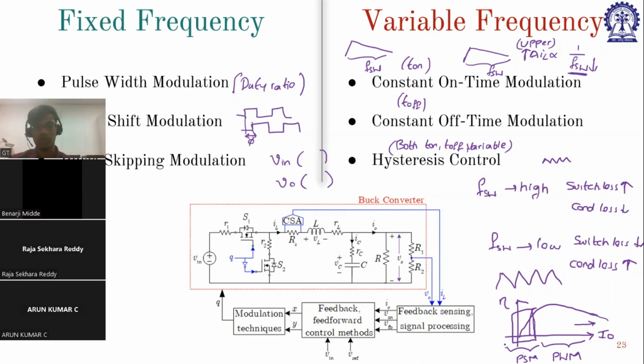Okay, during some cases, even if we select the inductor having, say, 20% peak to peak ripple, while designing or choosing this L, we will be considering the peak, maximum load current. Worst case, yes, for everything you'll consider the worst case. But what I have seen is that even if I have designed it for that case, the peak-to-peak ripple current is actually going to 200 or 300 times the load current, but still the output ripple voltage is only 30 or 40 millivolt maximum. Yes, but what is the reason behind this?